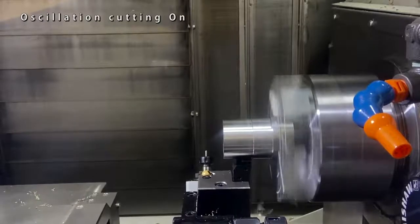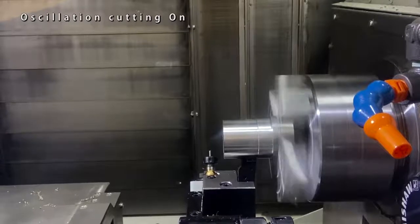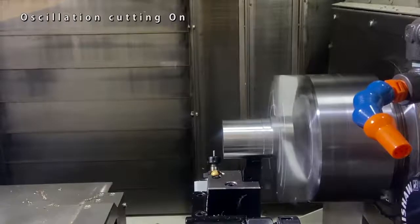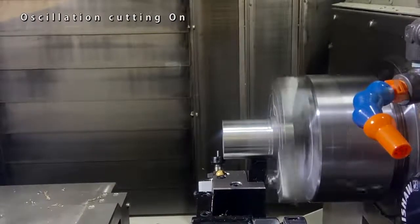Then we will start to turn on oscillation. You can clearly see cutting chips are divided into short pieces. You can turn it on and off even in a single tool path by just inserting G code.